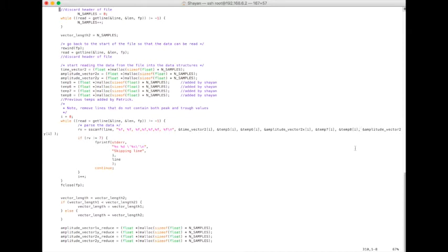Now, the motion data output file includes the following columns: sample time, axle X, axle Y, axle Z, gyro X, gyro Y, gyro Z, and magneto X, magneto Y, and magneto Z. And that is for 2 sensors. Now, by moving the amplitude vector 2x and amplitude vector 2y in the correct position, you can choose which column of the motion data output file you would like to perform the cross correlation and autocorrelation operations on.